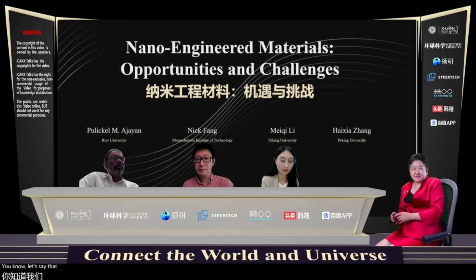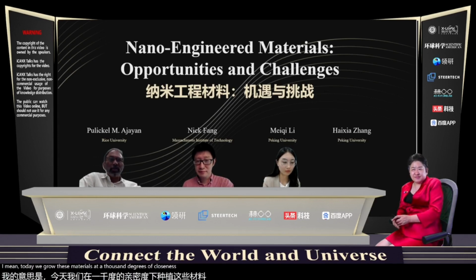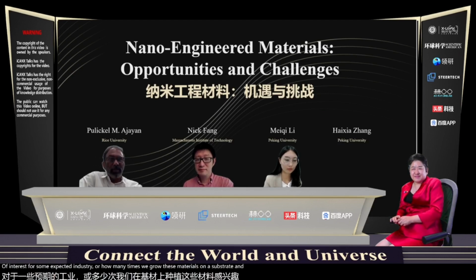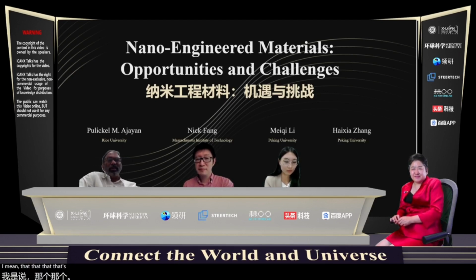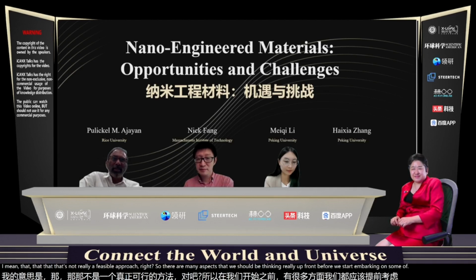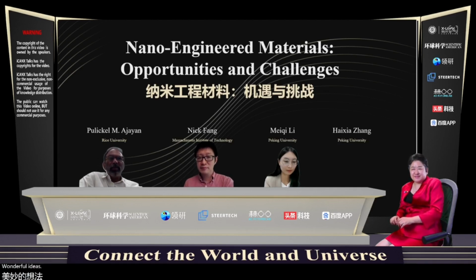Let's say that you're going to look at a particular 2D material for electronic applications. I mean, today we grow these materials at 1,000 degrees or close to 1,000 degrees, right? That's really not going to work, right? If you were to directly deposit onto a substrate that is of interest for the semiconductor industry. Or, many times we grow these materials on a substrate and transfer them to another substrate. I mean, that's not really a feasible approach, right? So there are many aspects that we should be thinking really upfront before we start embarking on some of these wonderful ideas. So I think it's extremely important.